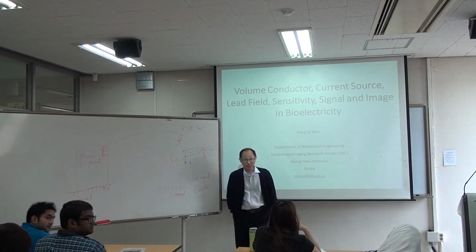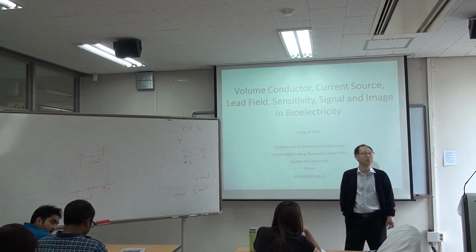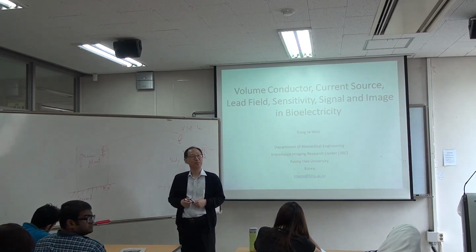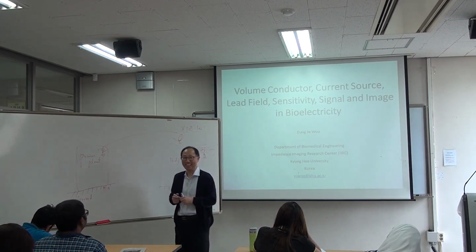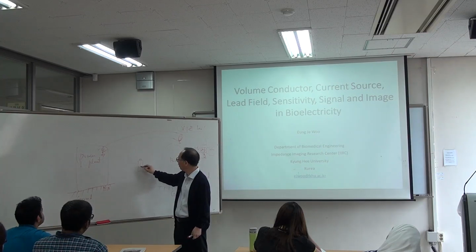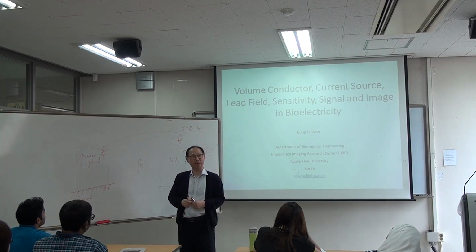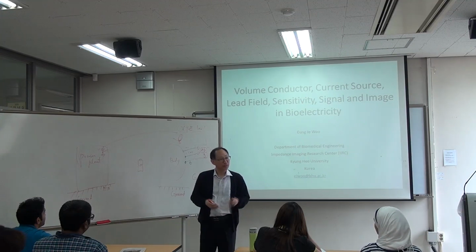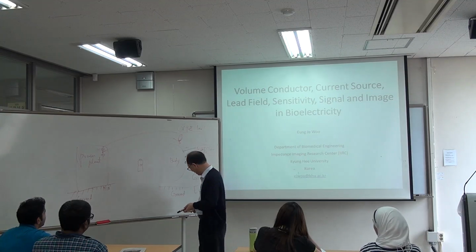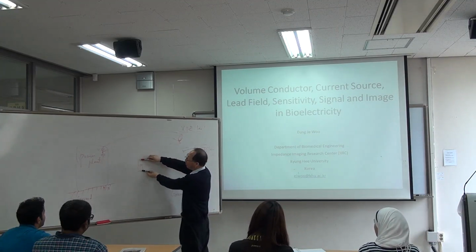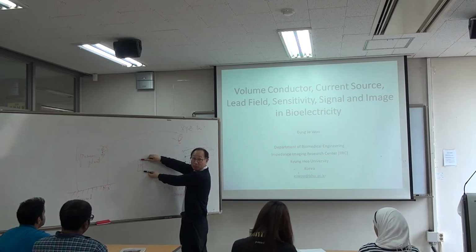What about the battery you talked about? If you add a battery, you said 3 volts. That will be in reference to ground. And then you connect to the body. So, that's also a very common question. You can buy a 1.5 volt battery from the store, right? You can find a multimeter. And you measure voltage between these points. This is the reference. What's going to be the voltage readout? 1.5 volt.